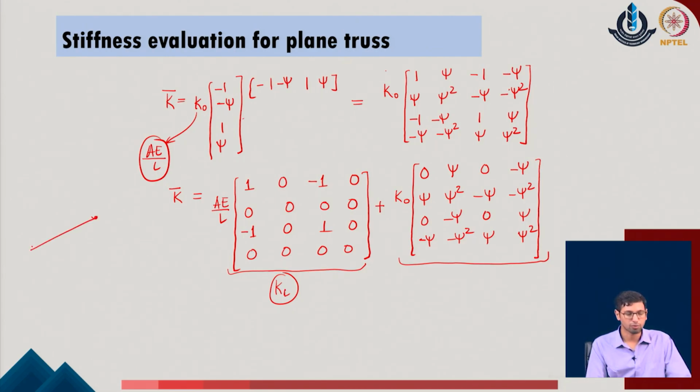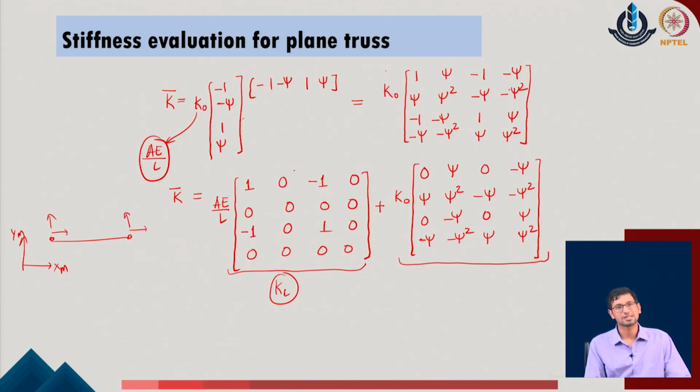So, if you have a truss problem and you locate the given member of the truss, defined in the local member coordinates, say x of m, y of m, and at this position we have defined these degrees of freedom, we locate this as a standard stiffness matrix for the given system. What we have got as the second part is the contribution of the nonlinear stiffness of the given system, and this nonlinear contribution is provided by the large displacement terms.